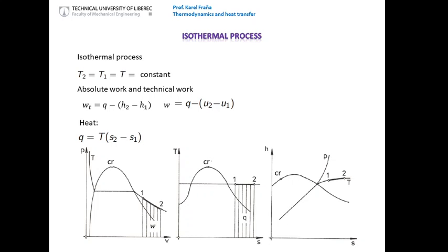In the entropy and enthalpy diagram, the line of the isothermal process is a little bit different. So the slope is different. You can see that it cannot increase so fast, and again you have to remember how to indicate this process in this area.